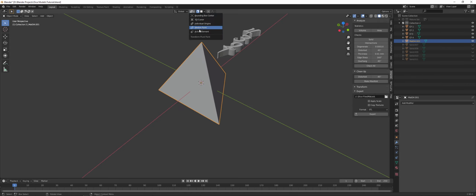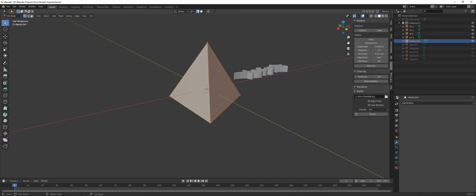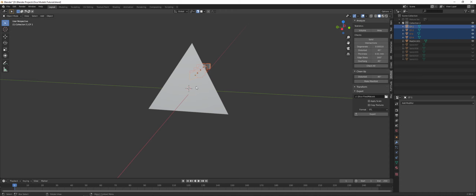You go into median point, you go into edit mode with the die selected, choose the face, Ctrl S, cursor to selected. Now you go out of edit mode, select all of your numbers, use snap to align them, then Shift S and select into cursor.